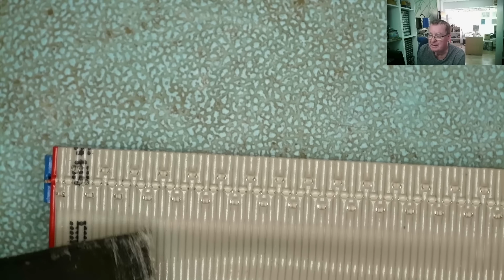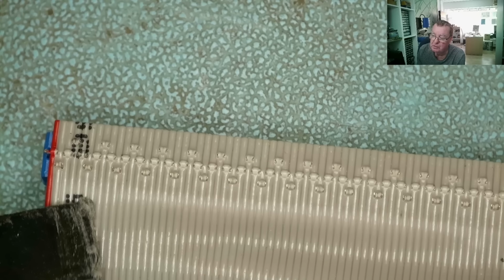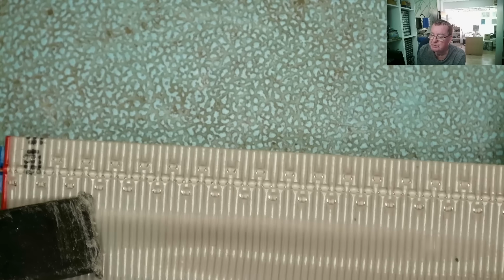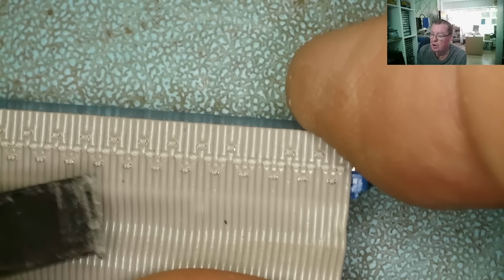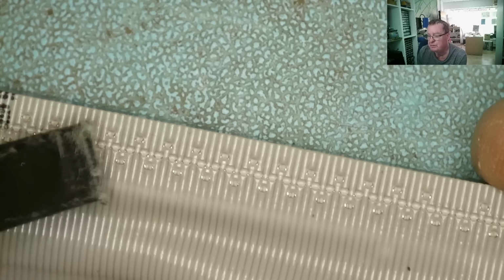When it's clamped together, the cable is pushed onto that. This cuts into the insulation and makes a contact with the conductor. So that is the insulation displacement. These are quite common to fail, especially ones that are being plugged and unplugged, or maybe even just because you were repairing something and unplugged them.